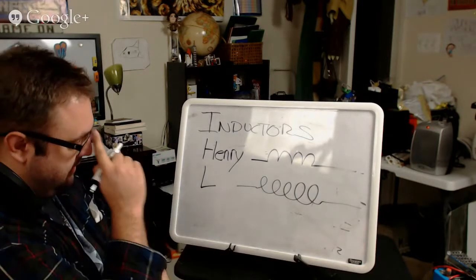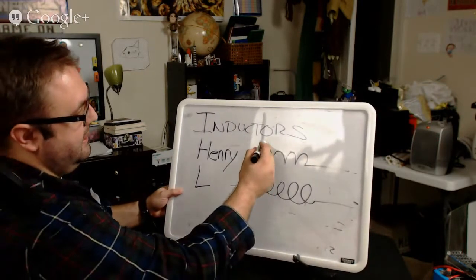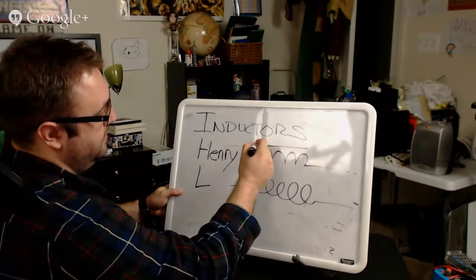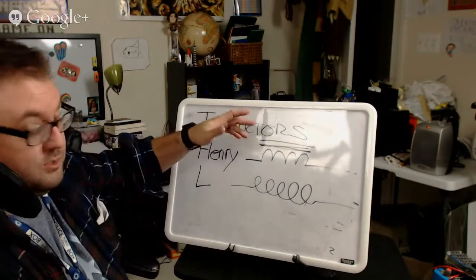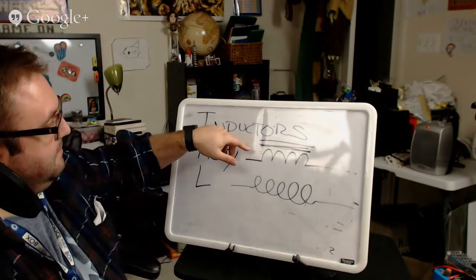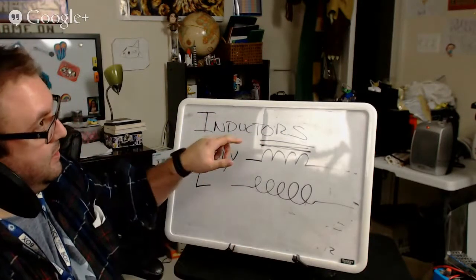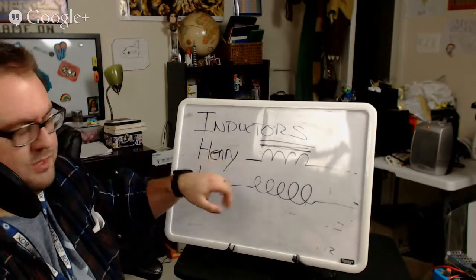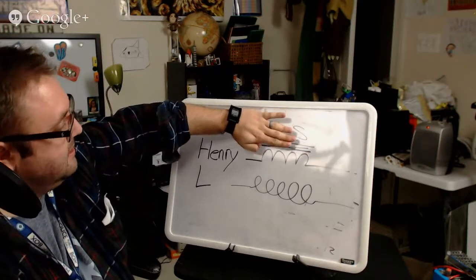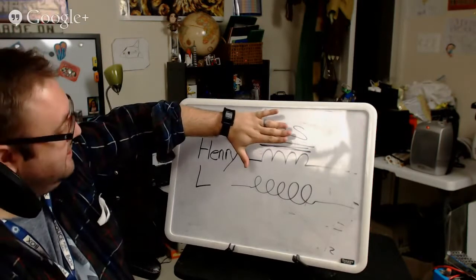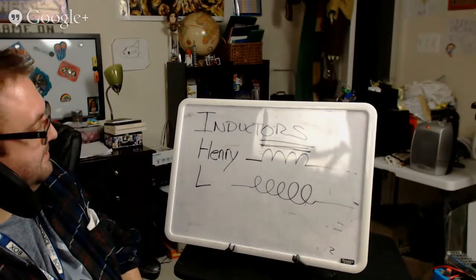And there's also going to be another symbol. If it has an iron core, we'll put some sort of symbol to show that there's something ferrous. Usually it's an iron core to help concentrate the magnetic field that's induced, and we'll get to that in a minute. Or if it's an air wound inductor, it won't have the two little lines above it.